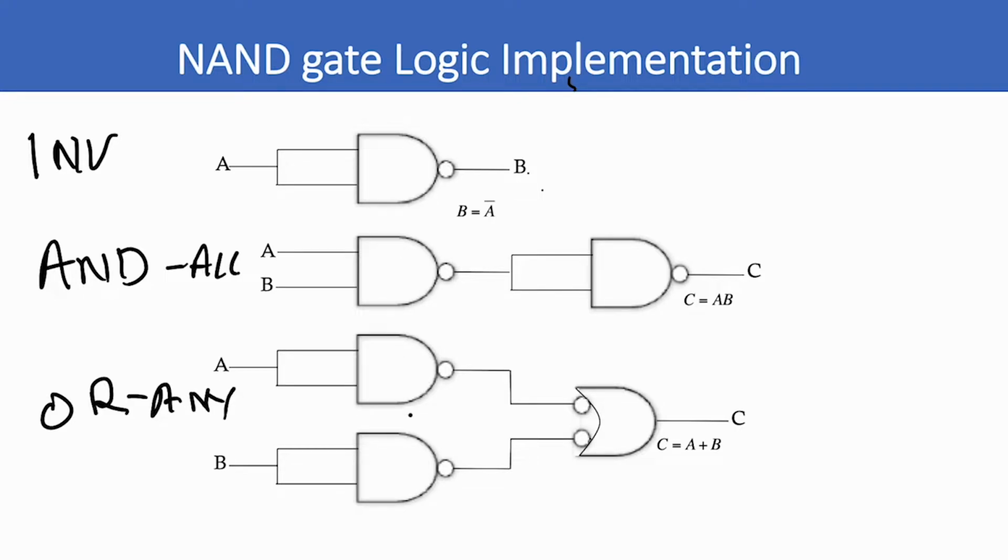Okay, let's look at these NAND gate implementations. Well, we know that for this one, because the two inputs are tied together, anytime A is a 1, both the inputs are a 1 and the output is going to be a low. So it inverts a 1 to a 0. And the alternate representation says that for this NAND gate, any low gives a high.